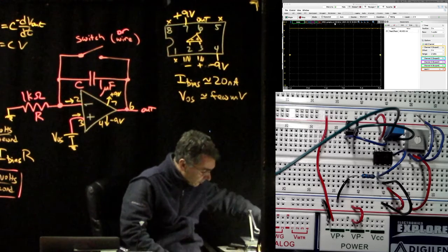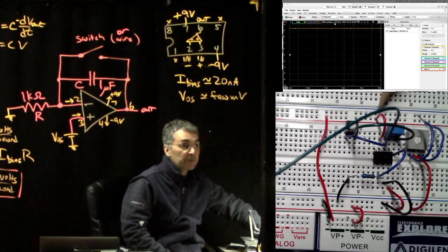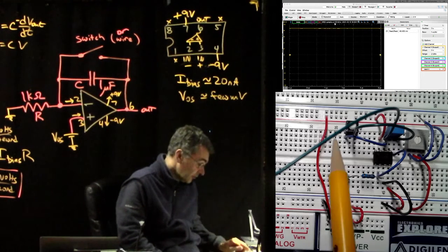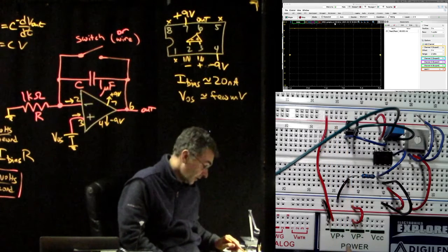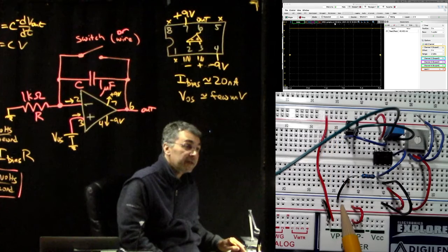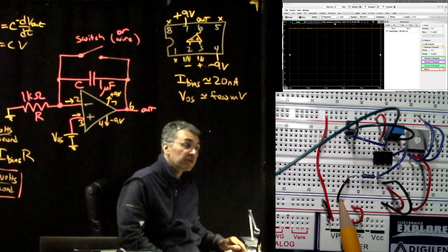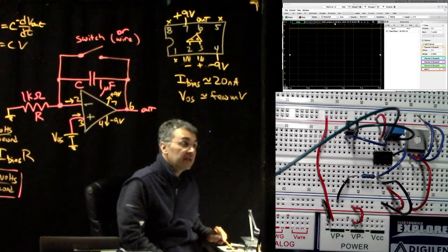Oh, and then I guess, right, pin 7 now is connected to this little red wire up to my positive 9 volts. So my convention is I like to use this top red row for plus 9 volts, this bottom red row for minus 9 volts, and then this bottom blue row I use for ground. And I haven't found a use yet for this top blue row.